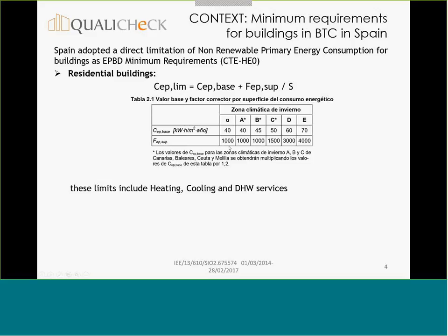And you see, it's a formula which is a number, the limit of energy base, plus a term which is depending on the size of the building. This is the surface, the area of the building. Then, as the building is bigger, the limit is lower.